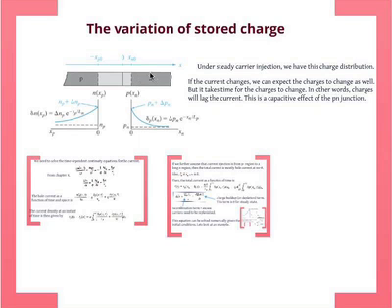When you apply forward bias, of course, our picture we saw before is essentially the holes from here, the majority carriers, get injected across the junction, and then become minority carriers, and then they diffuse. That's the mechanism for the current. They create a distribution which looks like this.